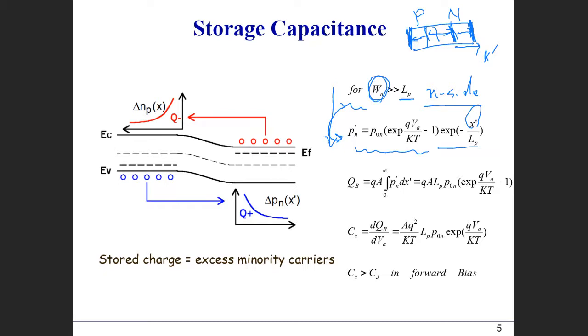Now, to calculate the total number of charge that exists in this neutral region on the N side, we're just going to integrate this from the depletion edge all the way out. In this case, let's just choose x prime as a very large value going to infinity, and then we plug in this equation and integrate all this area. Then from there we can obtain the total number of charge. Okay. So the same number of charge is, as you know, induced on the opposite side, in the P side. Now, we're going to have the conclusion of the charge being this equation.